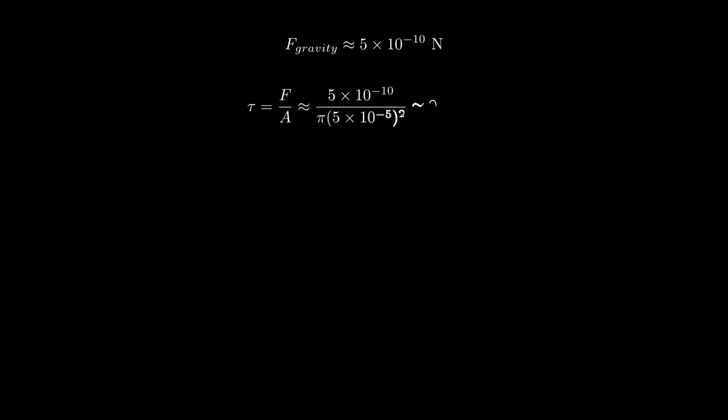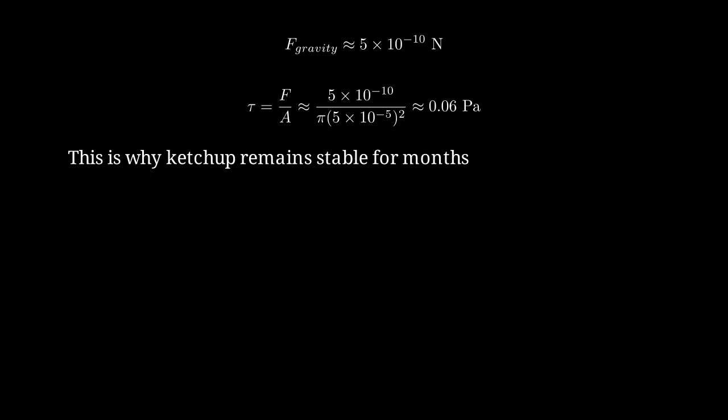The stress this creates is force over area, approximately 0.06 pascals. This is far below the 50 pascal yield stress, so the particle cannot settle. This is why ketchup remains perfectly stable for months or even years without separation, unlike simple suspensions.